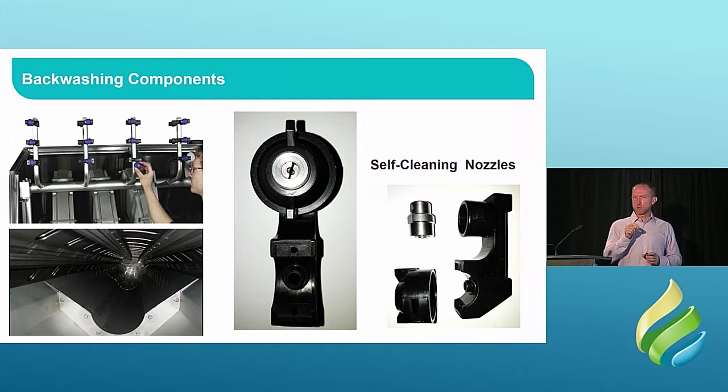When you think about it, the actual filtered water that's going through those nozzles is filtered down to, typically, 10 microns. It's a sort of cloth mesh opening. And if you've got a 10 micron filtered water and a 1 millimeter jet, then it seems strange that it would block. But what you have to remember is that this is wastewater. So stuff grows in those pipes, in all that manifold and piping. So over time, a bit of biological growth, a bit of biofilm kind of stuff growing. It's going to get sloughed off every now and again, get into those jets, and that's what's causing the block. So the self-cleaning nozzle avoids the need to have to unblock things.